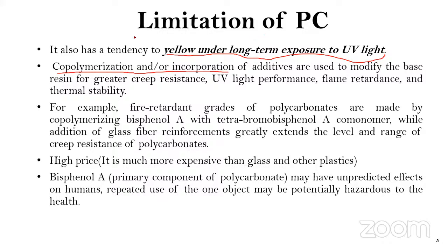So here the copolymerization or the incorporation of additives is used to modify the base resin for greater creep resistance, UV light performance, flame retardance, and thermal stability.